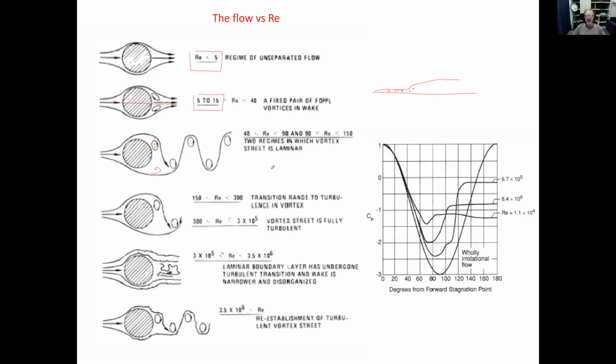But if you look at the wake, the vortices in the back, they're starting to generate turbulent flow behind them. Okay, and then you start getting to what we call the high Reynolds number range, which is say 10 to the 5th.